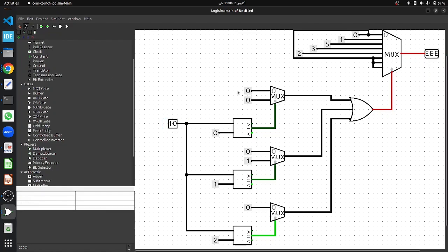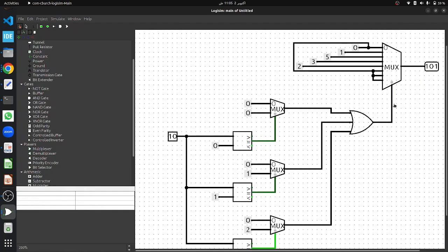So just to test it out, what if I place a constant value of 2 here, right? What do you think will be happening here if I change this to 2 and we simulate it again? You can see here that the red lines have gone black again, so the simulation is working correctly. I am getting an output of 2 here from the mux side, which is getting ORed with all these inputs. So the OR output will be 2. You can see the output at the control mux side is 1 0 1, which is the second input of the mux. So you cannot place the 2 directly here because we need to make logic for all 3 inputs, which are 5, 3 and 2.